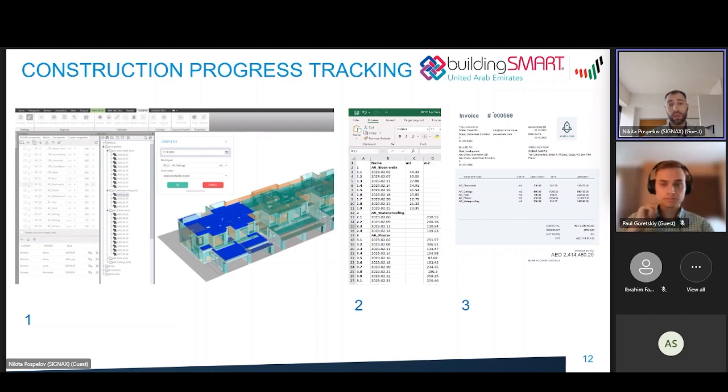As a final document, we generate accepted works invoices directly from the Navisworks interface. Moreover, we attach visual 3D images of elements only included on selected dates or work trades for more informative documents. To help with that process, we have implemented 360-degree image capturing, aerial drone surveys, and laser or LiDAR scanning inside the buildings. Which one to choose for certain projects? It depends on project size, schedule, and budget. All metrics are compared to ROI ratio.